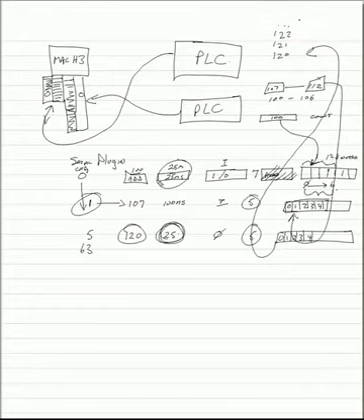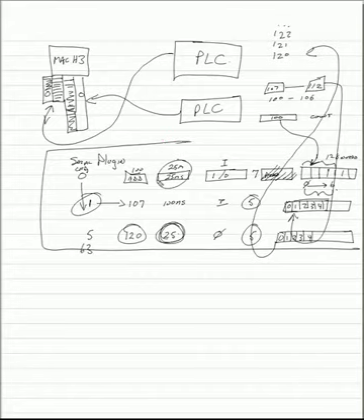You get the idea. So this configuration of serial plugin is somewhat more powerful than the old serial ModBus. And if you're not using special processing with a ModIO, it may be the way to go, or if you want to design your own ModIO plugin. The weakness here is that there's no way yet to send a string to the ModIO, so you can't use the LCD display on it the way that you can with the old serial ModBus.